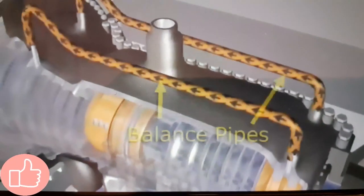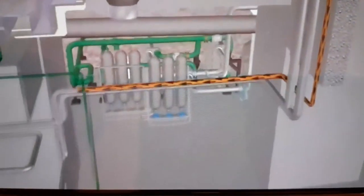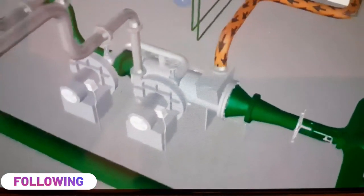As the main steam exits the high pressure turbine, some of that steam goes up through the balance pipes to the intermediate pressure section. More steam bleeds through the packing and goes out 2 pipes on the bottom of the casing. This bleed-off steam goes to the gland steam condenser.